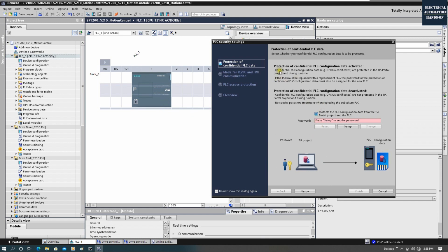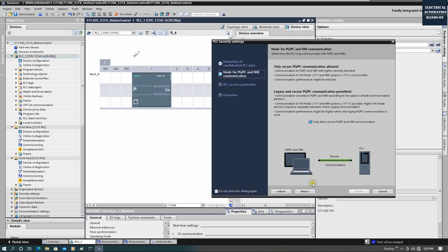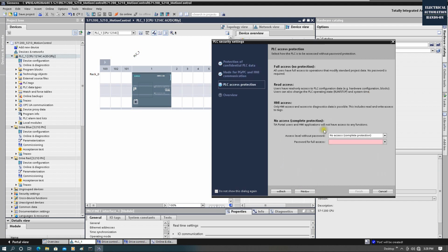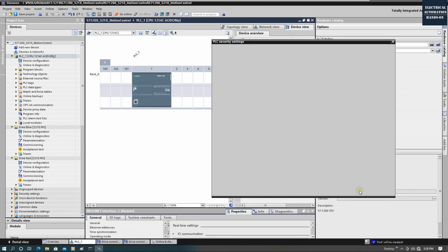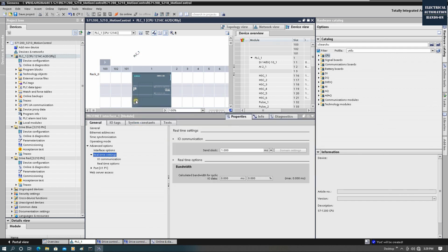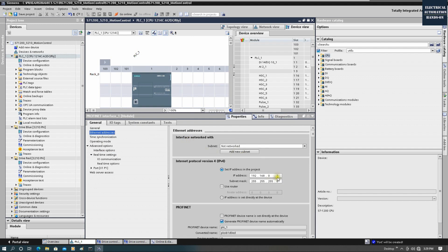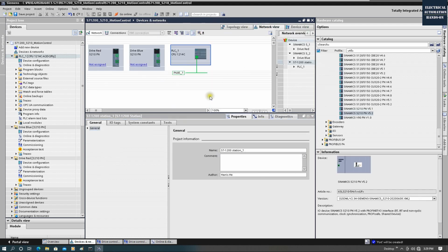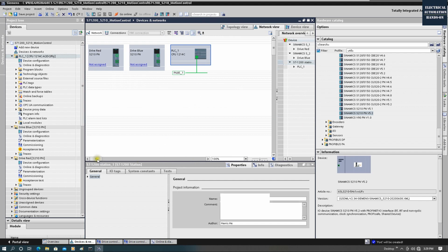So let's firstly go through this wizard, security wizard. So we can enable this, make this security all opened firstly. Okay. And then let's double click this device IP address, double check this IP address. Okay, 0.2. Okay, and now from the CPU side, we can activate a new subnet network, PNIE_1.